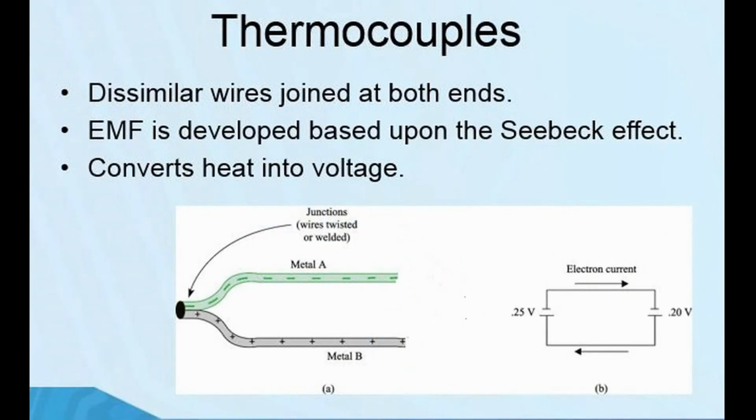Thermocouples are devices that use two different types of metallic wires, and that way when heat is applied, a little voltage will be created, which gives an idea of how much heat has been produced. The drawing in the diagram above is more correct than the book because it shows that in a thermocouple you have two wires, but one side is soldered together and on the other side the wires are free, and it is the free side that is attached to an electronic circuit. Once again, the signal will be very small and must be amplified.